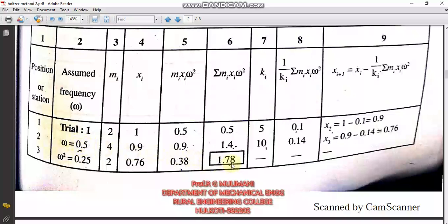Now you take all these natural frequencies on the x-axis and all these inertia forces, what is highlighted here in the rectangular box, on the y-axis. When you add all the points you will get this curve. You just find wherever you get the omega value as 0. So the first natural frequency is 0, the second natural frequency, where the curve crosses this x-axis, is 1.75, and again where this curve cuts the x-axis it is 2.85. So these are the 3 natural frequencies for this system.